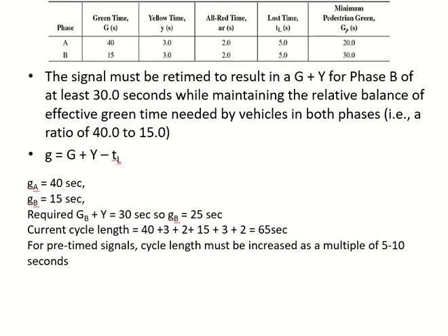So will the queue remain the same? No. The 40 seconds were enough for the queue which was only in the red of 15 seconds. When you increase the green time of this one, you increase the red time of this one. So more red time means a long queue. They should get more time as well, right?